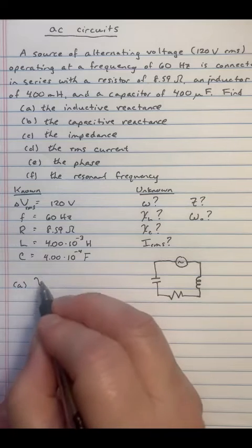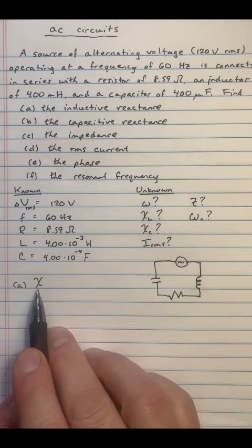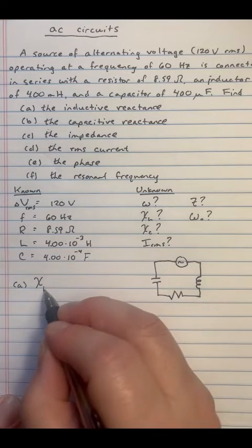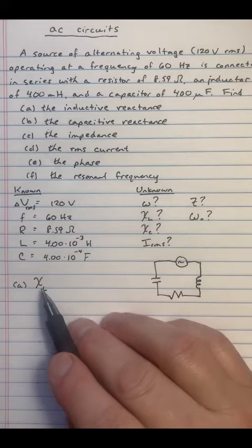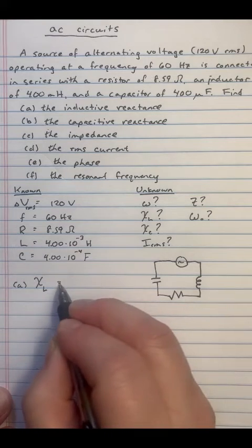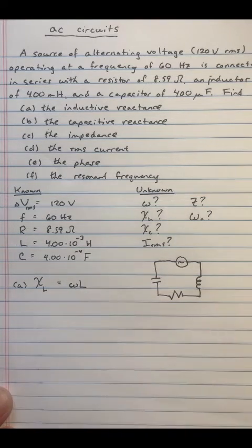The symbol for that is the Greek letter chi. That looks like an X because it is an X. In English, we sometimes have an X with a C or hard K sound, and that's maybe how to best remember it. Because there's more than one possible reactance, we do need to give it a subscript. That's L, so inductive reactance is what we're talking about there. It will still have the units of ohms because it's a situation where you're trying to impede the flow of current through it. But it's not resistance, so it's a little bit different. The formula for inductive reactance is omega L.